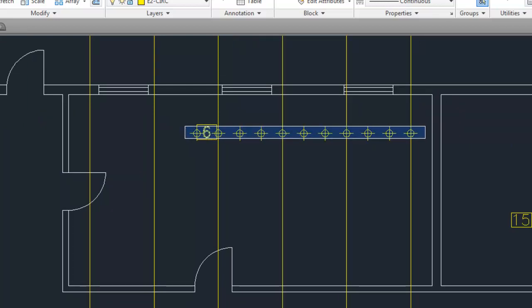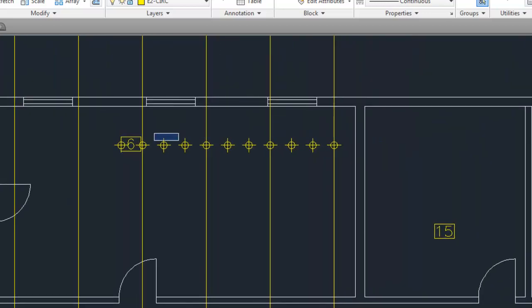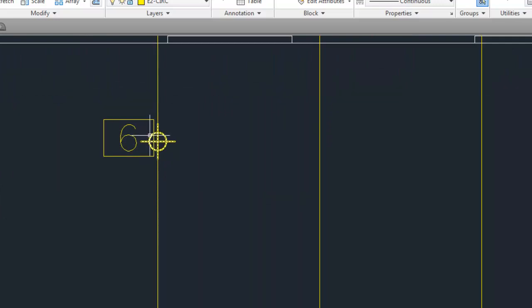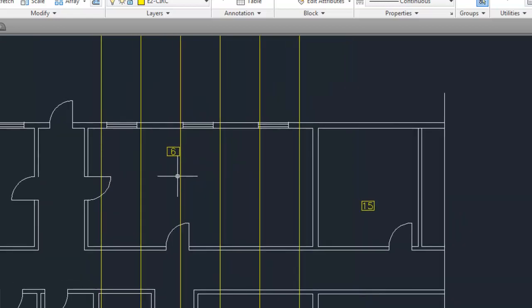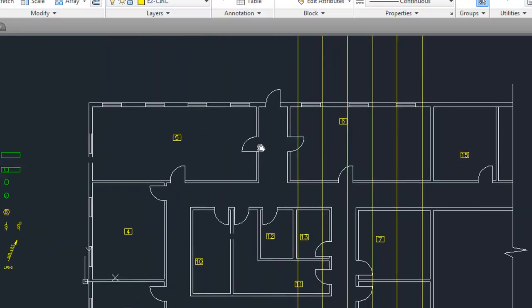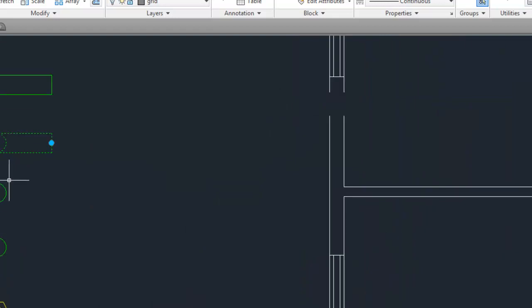So now we don't need these anymore because we've already got our spacing that we require, and we know exactly what the distance between these is going to be. If I wanted to double check to see how close it is to my 1.59, you can see that it's actually pretty darn close, 1.58824. Okay, so that's exactly what we were hoping for there, and it is evenly spaced. Now what I'm going to do is position my luminaires in this room. So the first one I'm going to choose is the one that has the junction box.